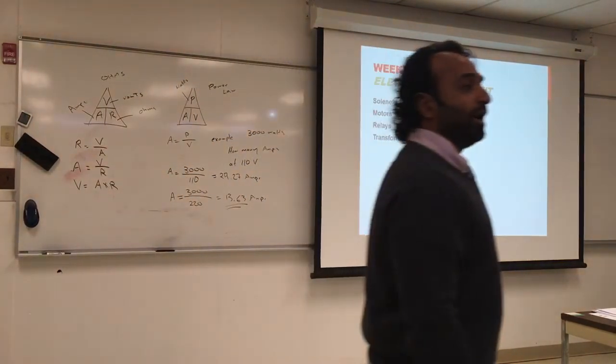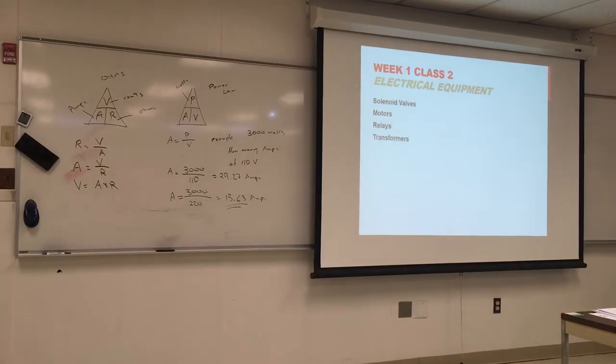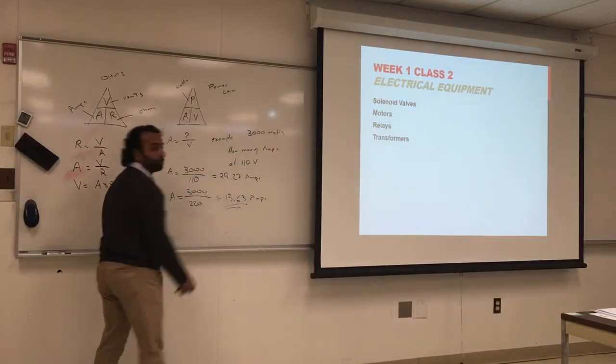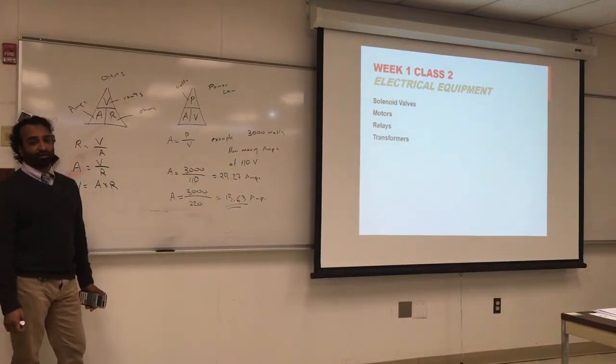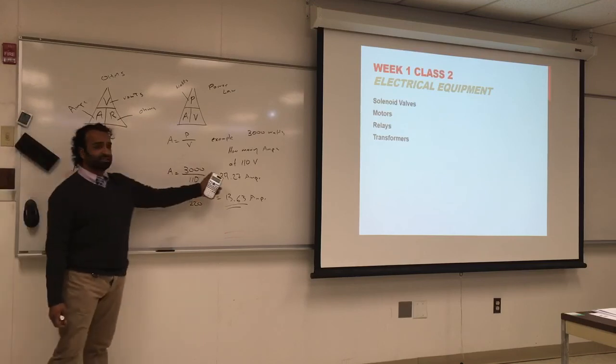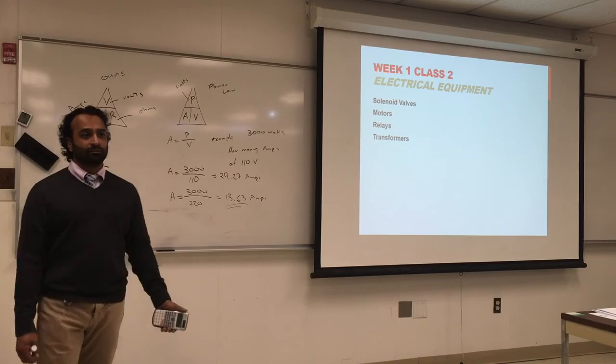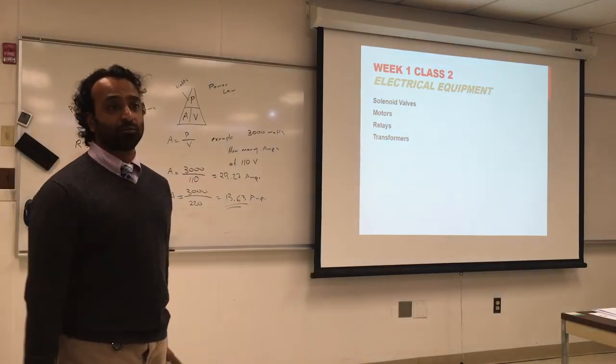And that's why in Europe and South America, I don't know, some countries are different, but everybody uses 220. We are the only ones who commonly use 110 for all appliances. That's why on your phone charger, you'll see it's between 110 and 220. We try to accommodate more countries. So I'm going to lower the load in the circuit, which is better. Instead of drawing 27, I'm going to draw 13 amps. The circuit is going to be cooler. The wire could be smaller.